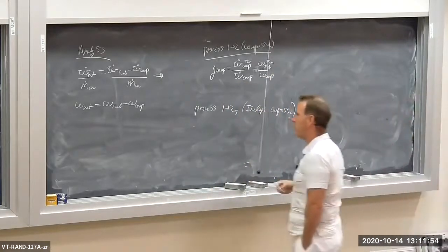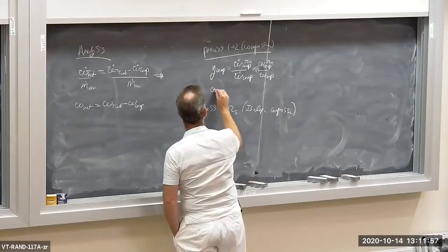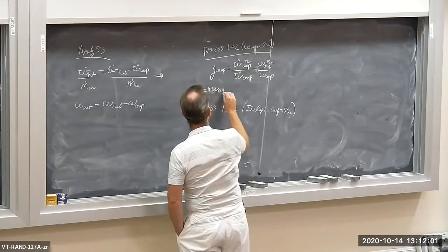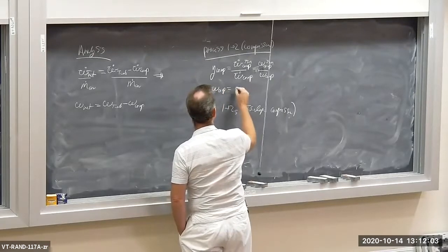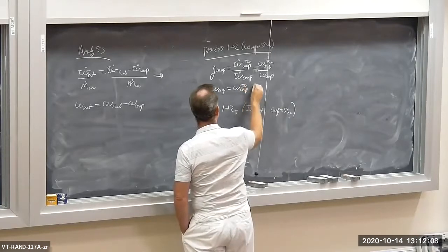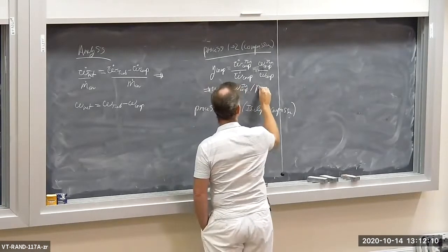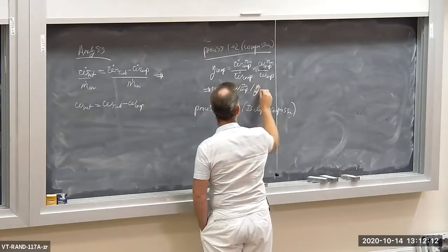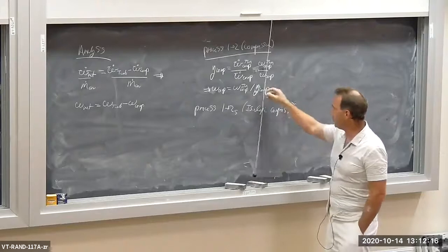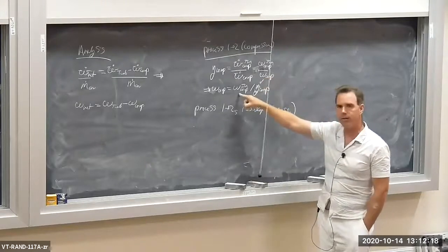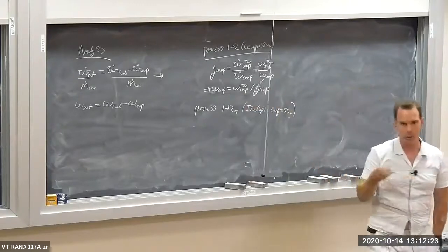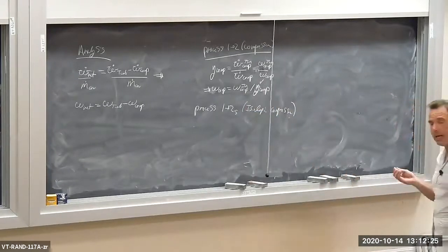And therefore, the real compressor work, W compressor, is equal to the isentropic compressor specific work divided by the isentropic efficiency. Now, I have the isentropic efficiency. I don't have the specific work for the isentropic compressor, but maybe I can get it.